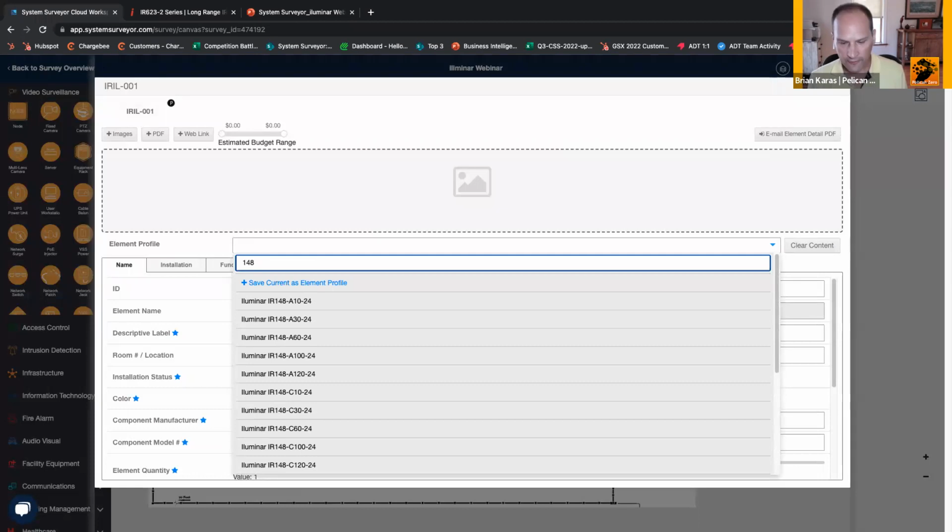So for outdoor scenarios, we usually recommend that the illuminator be placed relatively near the camera, usually a little bit above it, looking out over the exact same field of view, so that your illumination cone is basically matching your camera's field of view cone. Indoor, you'll have a little more flexibility with illuminator placement. It might make sense for a lot of reasons to have it right next to the camera, but as long as it's not shining into the camera, of course, you can move it.